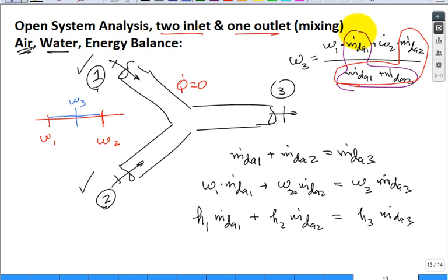What happens if somebody says, oh no, this ratio is 0.9, hence this ratio in red is 0.1? Well, you have a straight line, and you would divide it 90% and 10%, and it would be way over here, right? This length of the line would be 0.1 and this length of the line 0.9. We're preparing you for the psychrometric chart. We put a straight line on the psychrometric chart, and we say, look at that, it's a ratio, a mixing, and it's 90%, 10%, or 50%, 60%, whatever.